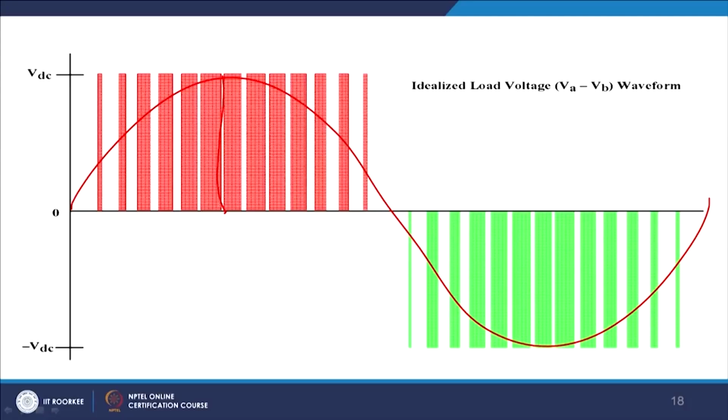Another advantage is that it eliminates a huge amount of harmonics. Why? Because it forms a notch in this zero potential. So, in that way many undesirable harmonics are truncated, and moreover, instead of the dominating frequency being shifted to F after the fundamental, it will be transferred to 2F.